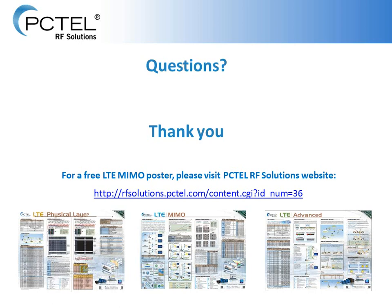So we can measure all 4 of those paths and provide reference signal receive power, RSRQ, receive quality, as well as the SINR or CINR on all of those paths where you're transmitting from the eNodeB to the receiver. Okay. Next question, I think we answered part of this: is the MX capable of measuring multipath? Yes. We actually do measure multipath.